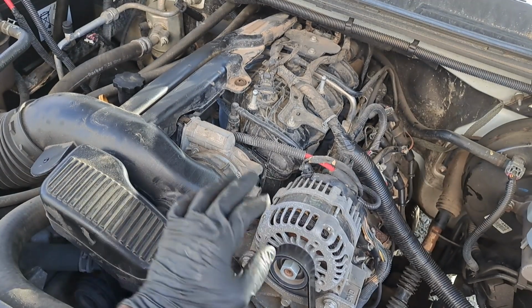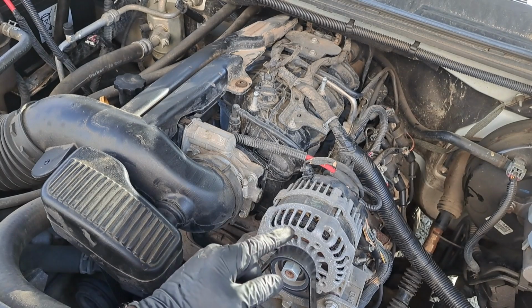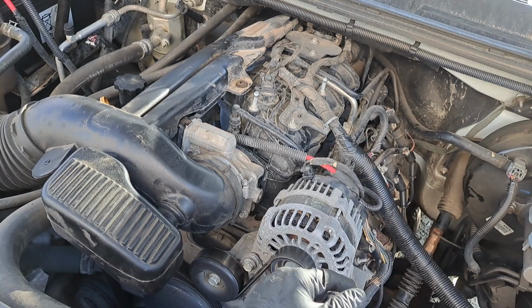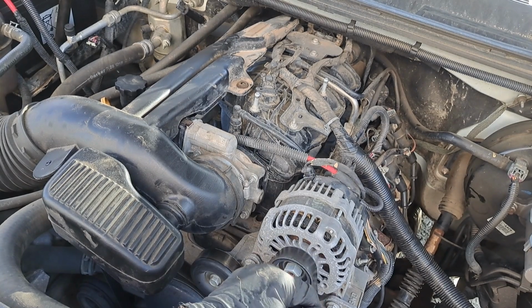It ate that brake cleaner up pretty good. Let me clear the codes, if any, generated through that startup from any misfires or any rich codes, see how the throttle body is responding, then take it on a test drive.